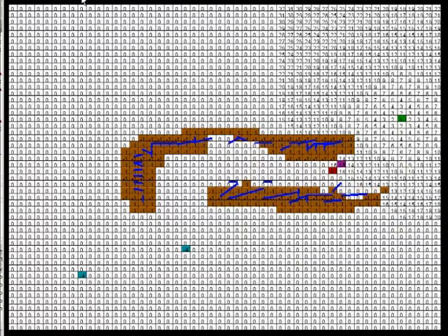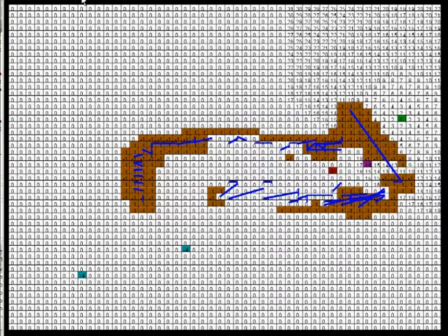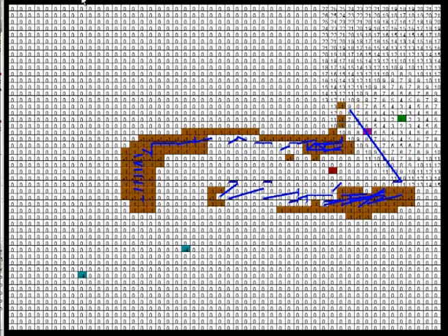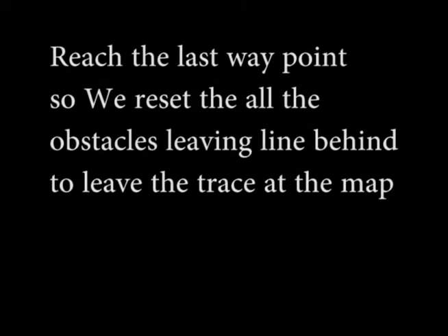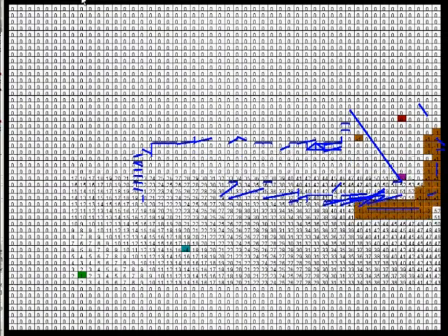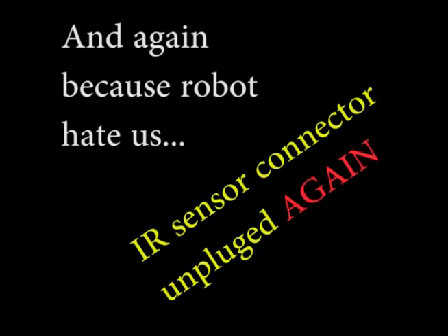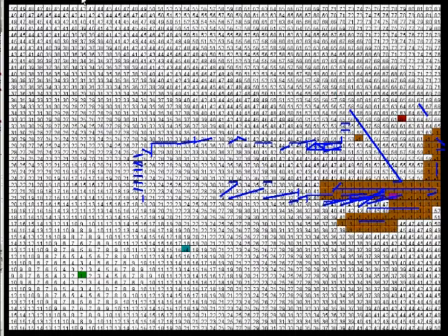Next, we're going to be talking about generating the local map. For the local map, we use an IR sensor, which is mounted on the front of the robot. It sweeps from negative 90 to 90 degrees from the initial sweep, and that scans pretty much every wall surrounding its front and back. Because the turret is a servo motor with an encoder, we know the exact angle of the IR sensor. That way we can figure out the exact location of the wall given the distance that the IR sensor returns, and that determines the location of obstacles and walls, which we then update to the global map.